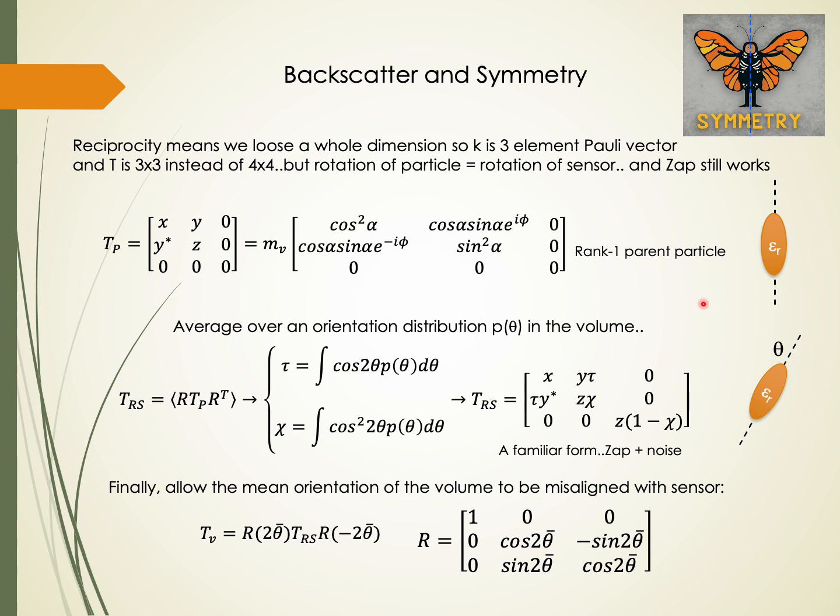Now, we started off by assuming that we were aligned with the reference particle in the coordinates, but maybe our radar might be misaligned with this. In other words, the particle itself might have some mean orientation in its distribution, and that may be different to the reference that we're using in the radar system. And so we have to allow for a mean offset in rotation, which we can do just by rotating this depolarizer model through an angle theta. And when we do that, we've now got the flexibility to allow for mismatch between radar and target.